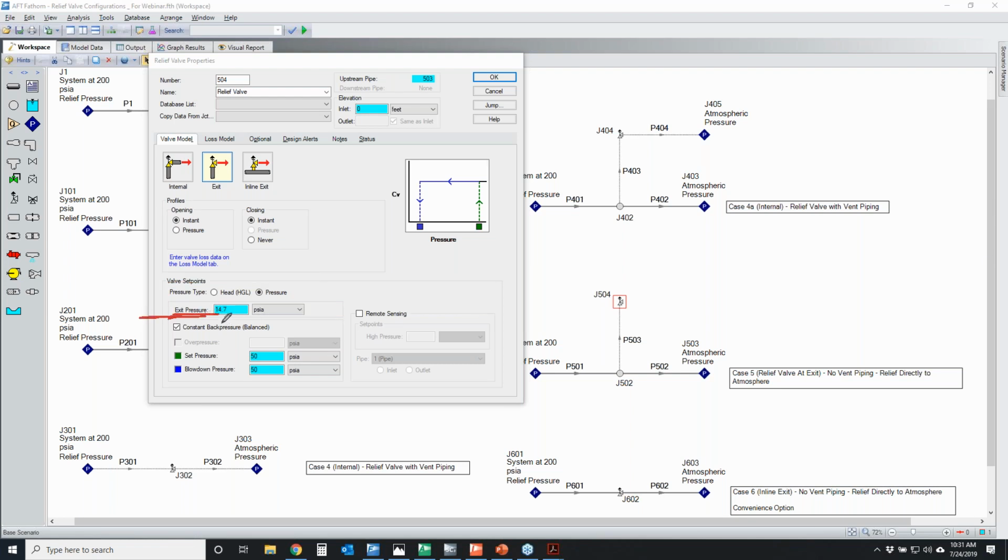So that is simply your ambient pressure, okay? If you're discharging into atmospheric, it's atmospheric pressure. If your relief valve is discharging right into the bottom of a lake, well, then it's going to be your surface pressure on the lake plus your rho gh term. So that's how that exit pressure is going to be defined accordingly.